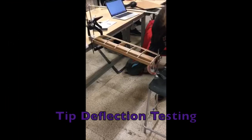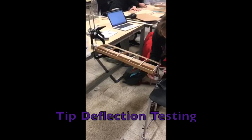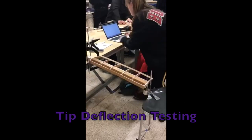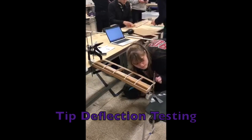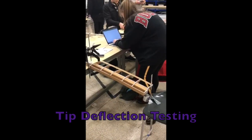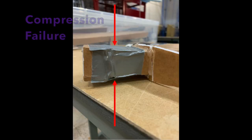Tip deflection was then calculated. The wing was clamped to the workbench and increasing masses were applied with the tip deflection measured at each mass. Failure occurred at 5.059 newton meters greater than 2.99 newton meters predicted. This may have been due to the glue and tape taking some of the stress and enabling a greater mass to be held. When the spar failed, compression failure was experienced near the wing root due to the clamp.